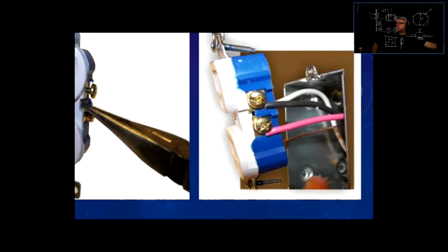All right, so of course, this is the example of the tap being broken, interrupted. So here we have one neutral wire going to the other side, which will be accommodating the neutral prongs. And over here we have a hot wire, black, going to the top part, and the hot wire, red, going to the bottom part.